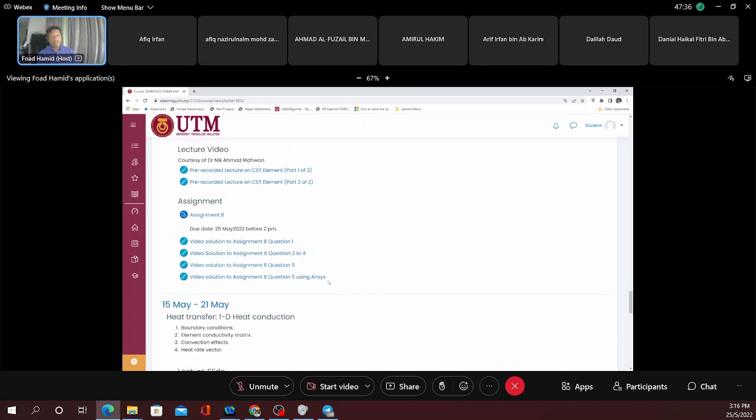that explains CST using ANSYS. Since the plate shown in figure 1 is symmetrical in both horizontal and vertical axis, the analysis can be done by using quarter model with appropriate boundary condition. Use a minimum of 12 triangular elements. The problem with ANSYS is it can use either rectangular or triangular. Rectangular elements we do not cover in this class.